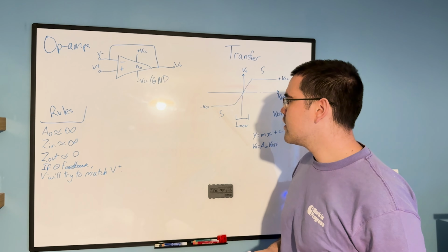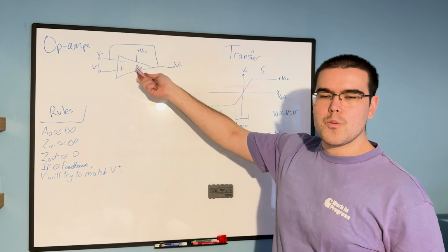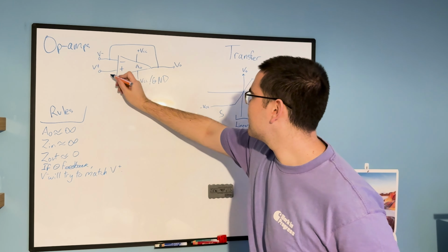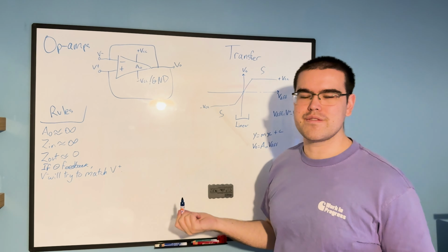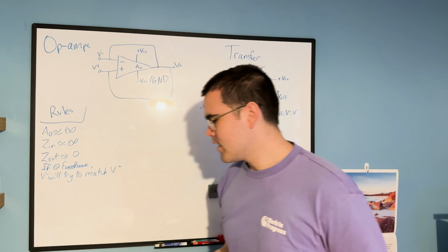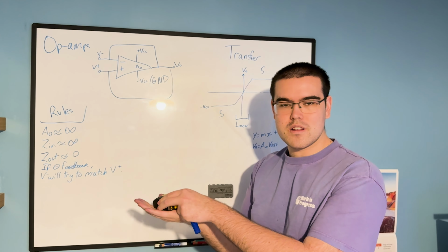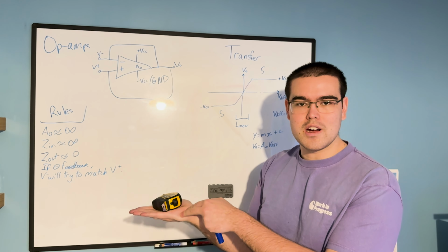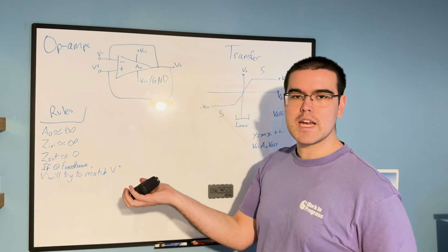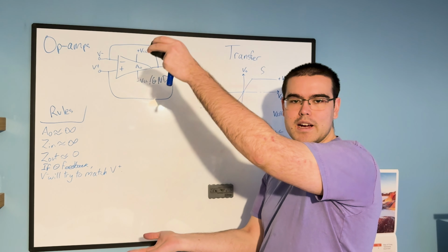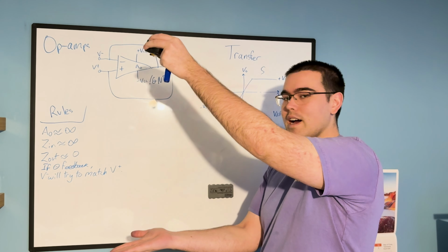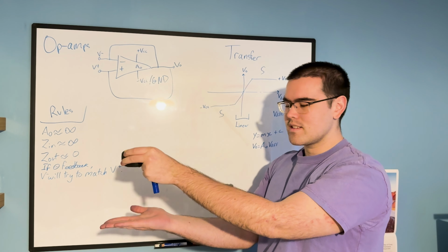So now that I've covered that, but how do we know which feedback to choose? Because we could have a negative feedback, but what will stop us from doing a positive feedback? What's the difference? Okay, so for example, I have this measuring tape, which is the signal, and my hand is the set point, the target of the signal. So if I throw this up, it will come back down. So this is negative feedback. I throw it up, oh no, I'm too far from the set point. What am I going to do? So it will actually go down. It will subtract the error.